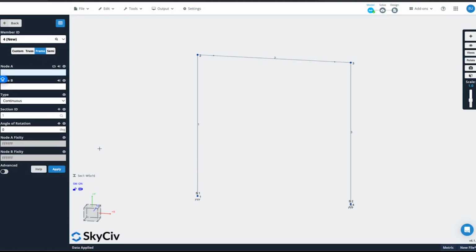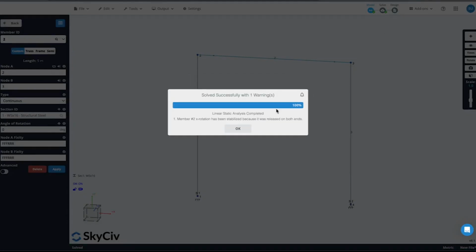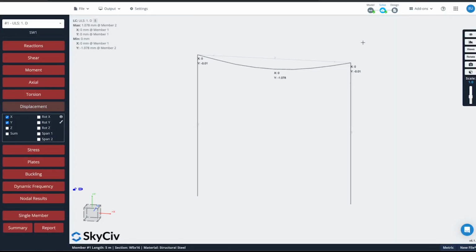And so this is going to be slightly similar to a truss element, at least at these nodes, in that the moment forces are going to be transferred out. So if I go here and solve again, you can see that the moment force that we're seeing here is not being transferred down to these members, because since this is released here, the self weight comes down, it's stressing this member by itself, but it's not being transferred into any of the other members as well.